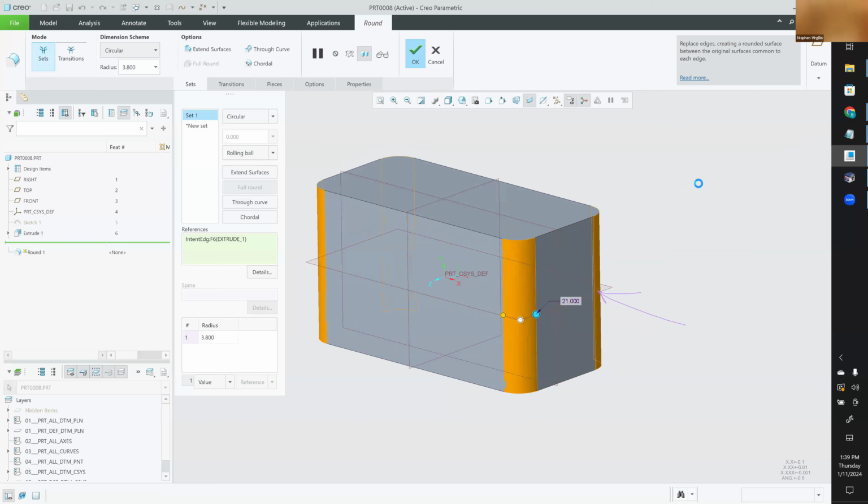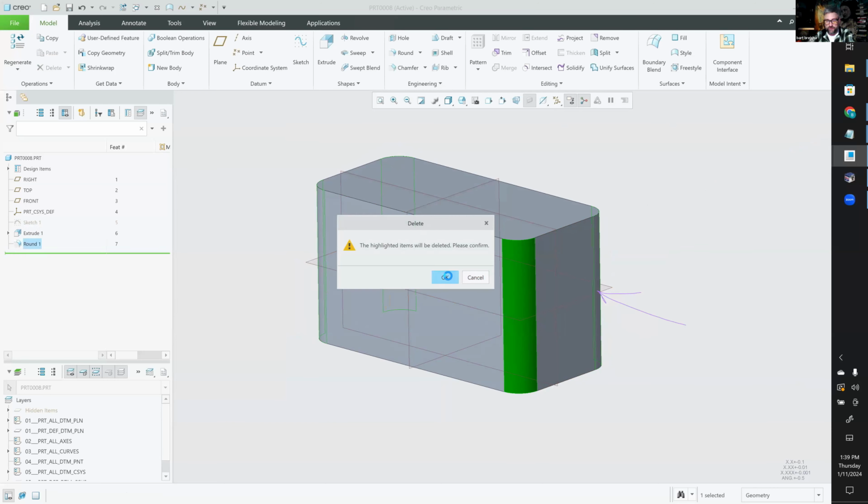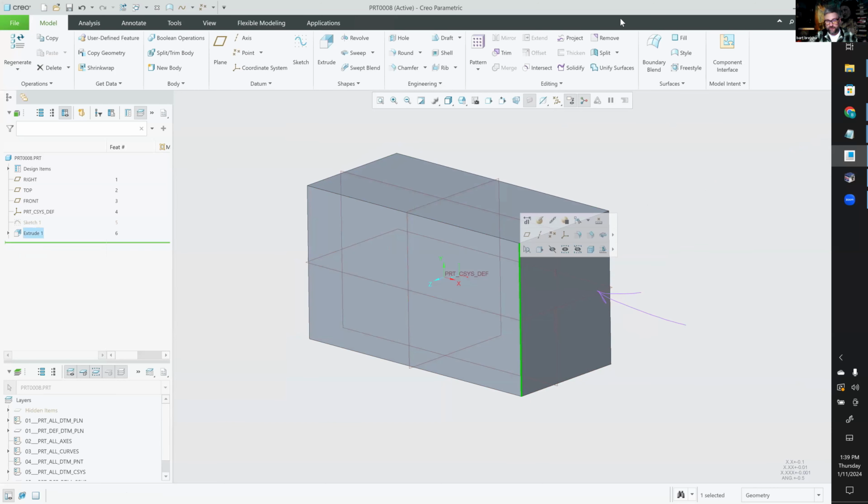I want to try control that. Now if I don't want some of those edges, say we had 16 edges there and I only want 14 of them. Yeah, I don't know if control's gonna let you deselect some of them. If you just pick one and hold the control key down, it's gonna fetch the ones that you want. Notice I didn't pick this far back one over here. But you could right click through here and grab that one too if you wanted to. I just did not. And when you let go of the control key, it's gonna bring this pop-up window.